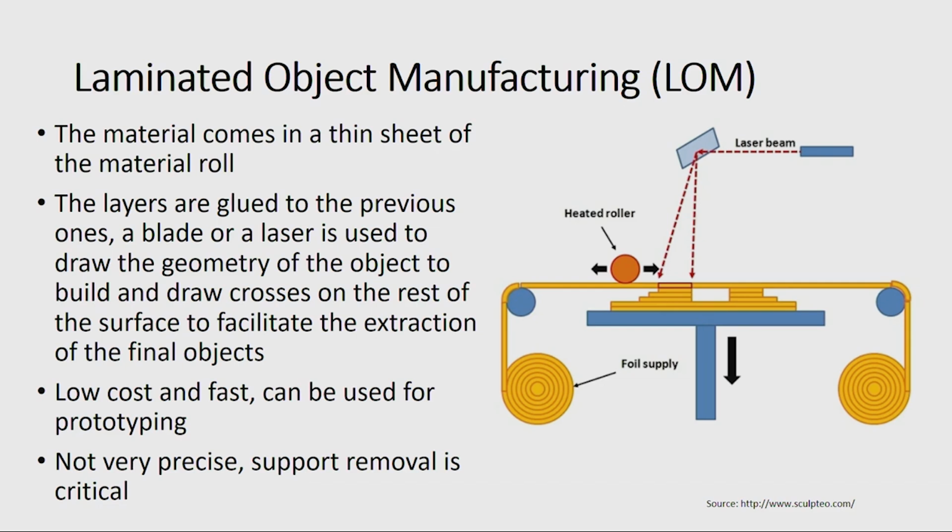You can see it will move from left side to right side, and the build plate will move down once a layer is completed. At the top there is a laser source and a mechanism for pointing the laser beam in the XY axis of the build plate.